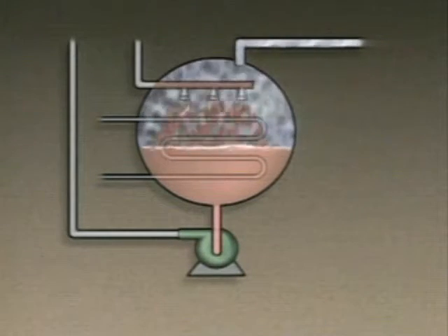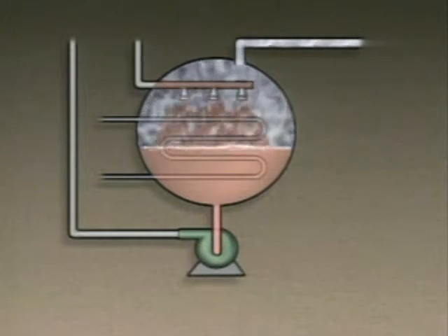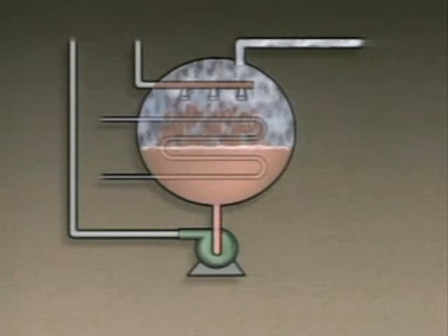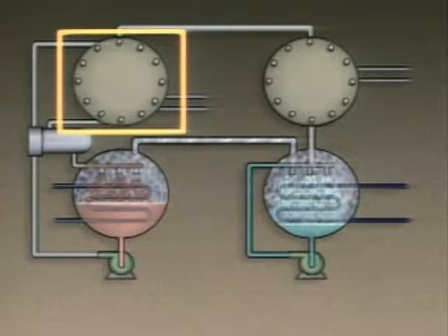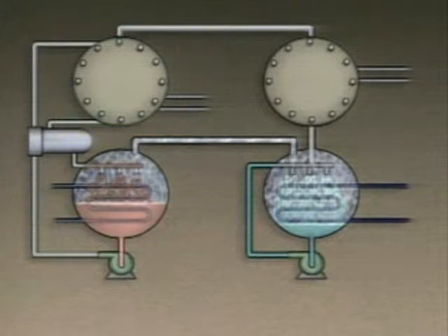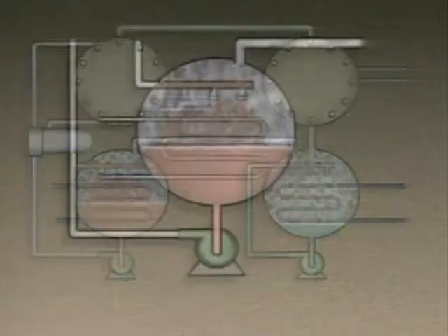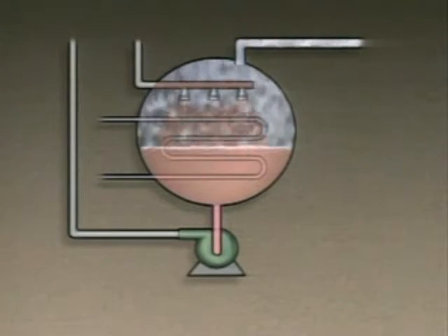The lithium bromide and the refrigerant will be reused in the system, but to do this, they must be separated. The separation takes place in the generator section, which means that the mixture, called weak absorbent, must be pumped to the generator. However, the weak absorbent is hot enough to boil inside a pump, so it must be cooled first. The cooling takes place in the absorber.